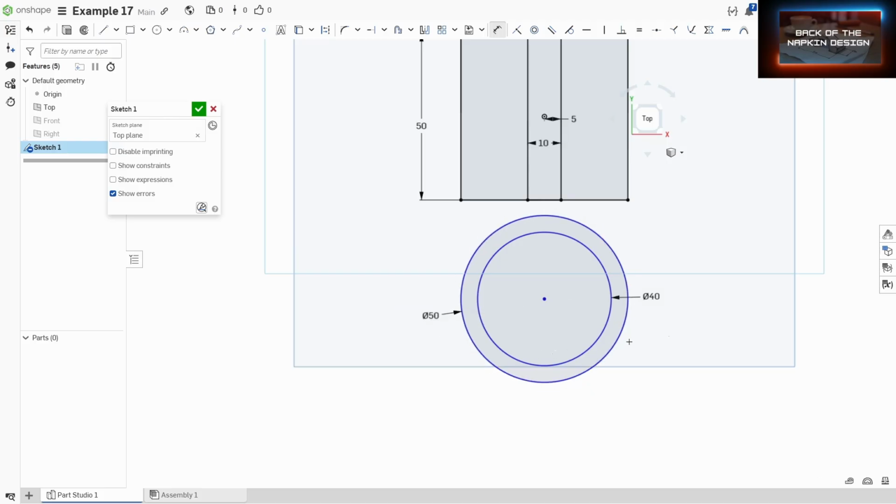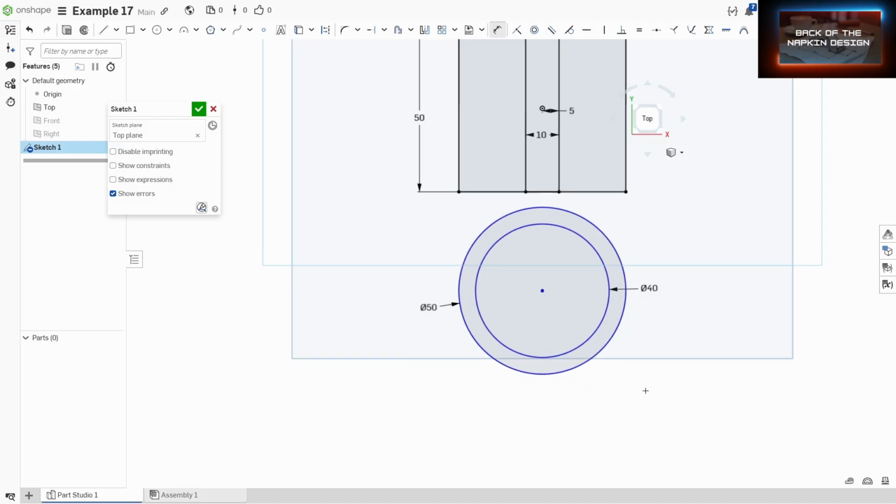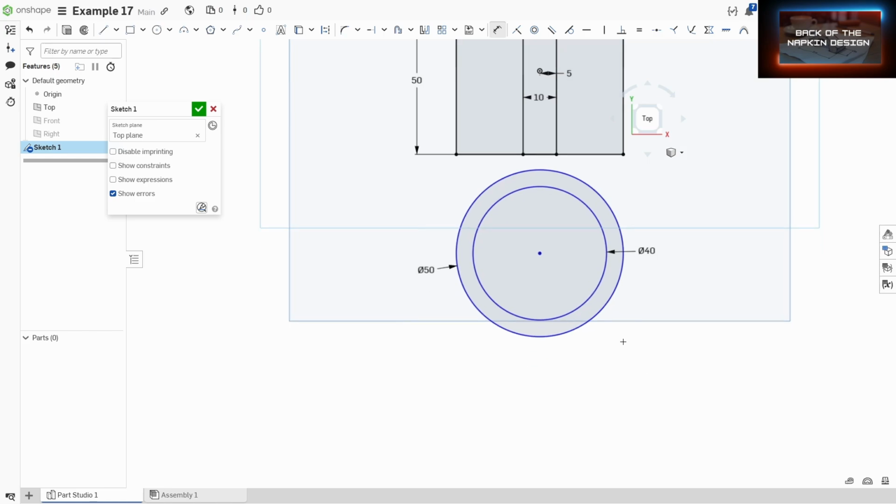Okay. So now I noticed that our drawing is missing a dimension, but I'll figure this out either way. So I'm going to draw a rectangle from here to here. And we're going to dimension this. So here, dimension to there, and we're going to go with 2 millimeters, and then we're going to go from left to right, and that's going to be 4 millimeters.